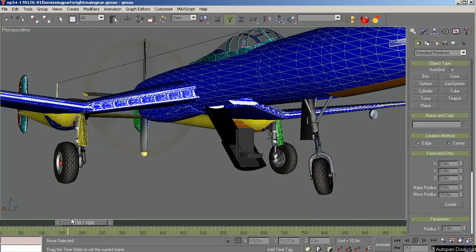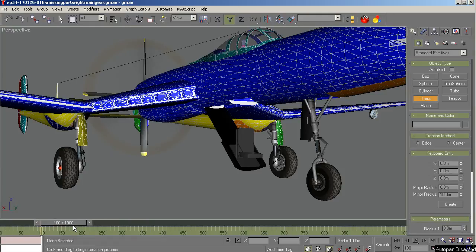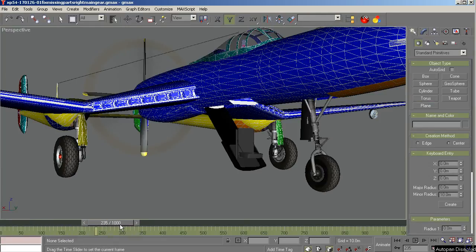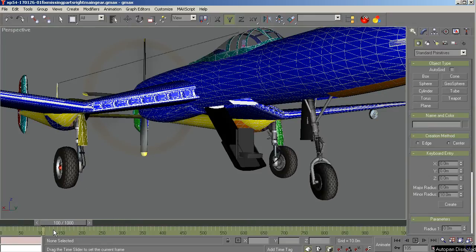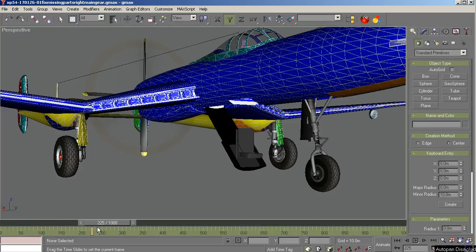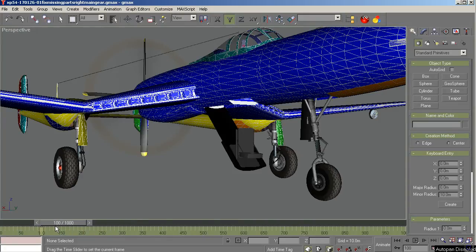In addition, you'll notice that the nose gear has a 360-degree turn in it. That animation represents a castering nose gear or tail wheel, either way. And that's how it's done in Gmax to set up the animation. So to make it easy, we'll do the suspension on the nose gear before we do the, what they call the C wheel, center wheel. Castering animation. Had a brain fade there.